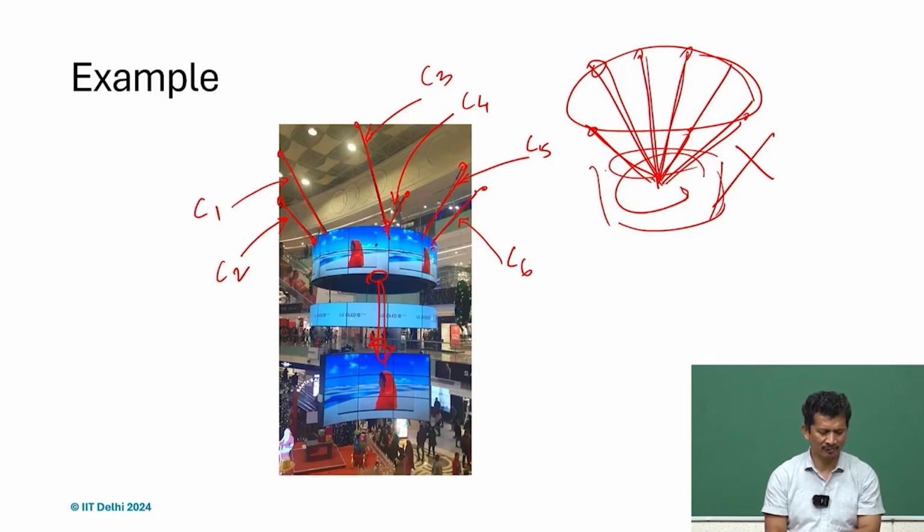So, maybe they were afraid that it may fall, but if you understand the concept, if you understand the exact constraint design, you know that it is not going to fall and it will constrain all degrees of freedom. And since it is very heavy, all the cables or the ropes will be under tension. So, no need to worry.